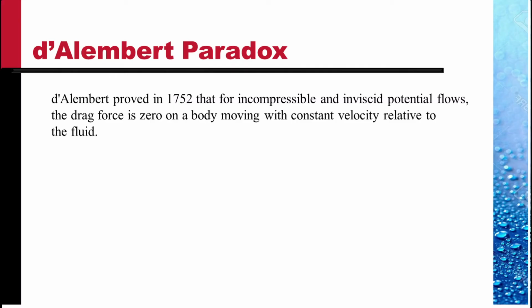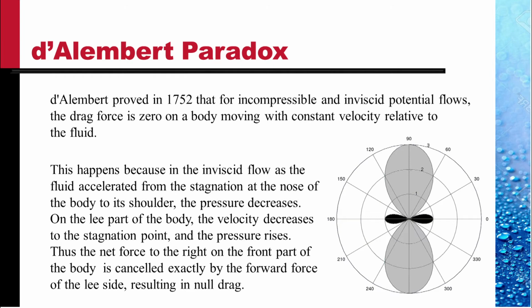D'Alembert proved that for incompressible and inviscid potential flows, the drag force is identically 0 on a body moving with constant velocity relative to a fluid. This happens because in the inviscid flow, as the fluid accelerates from the stagnation point at the nose to the shoulder, the pressure decreases. On the lee part of the body, the velocity decreases to the stagnation point and the pressure rises.